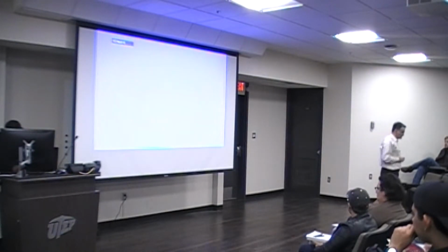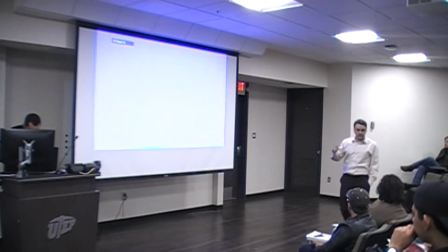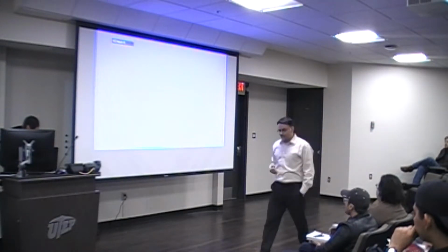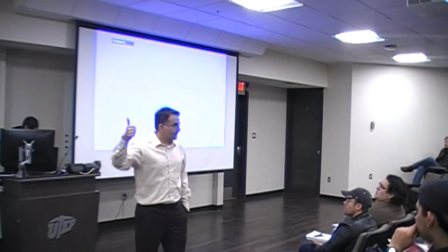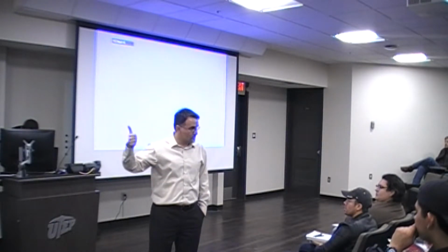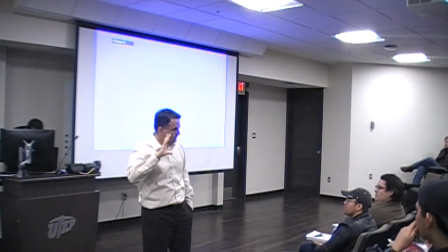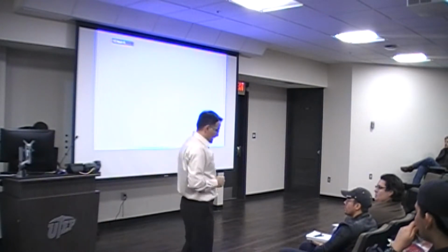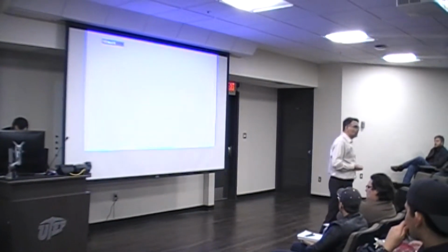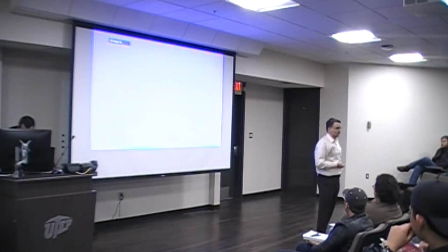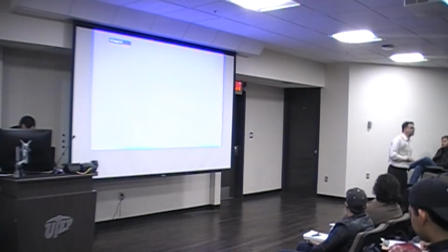All right, so soils are highly nonlinear material. The plastic strain component is significant, and therefore you have to be able to account for that. Now, the next component of the soil is that, remember, we're talking about non-homogeneous material, stress-sensitive material, meaning that the modulus value changes with the amount of stress that you apply on it. And they're nonlinear material as well. Now the fourth one on the list is that soils are anisotropic materials. What's the definition of anisotropy?